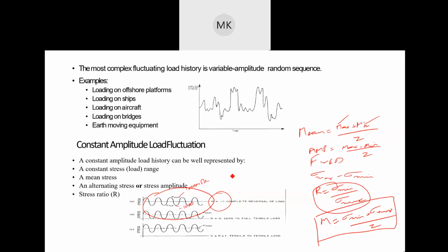There are major advantages of this and disadvantages of it. But in hindsight, every cycle you're going past zero. So that's something that can create crack closure effects in the material. And also, every time you load the material, you're actually opening up the crack again after crack initiation, so the environment can directly impact the crack growth in the material.